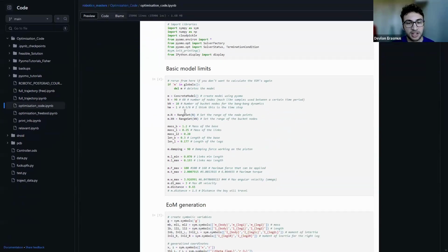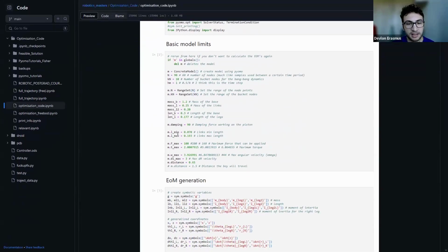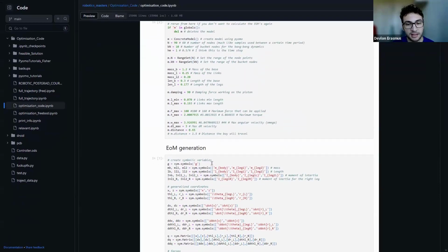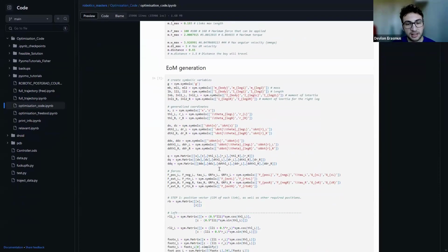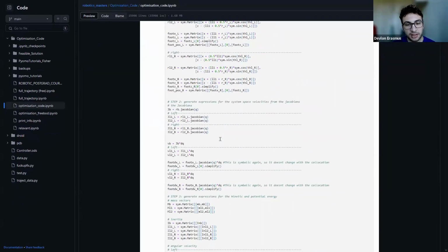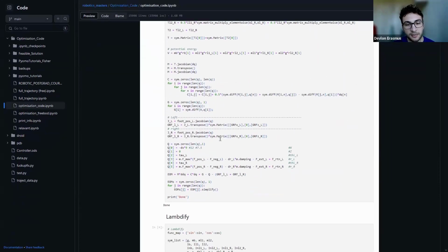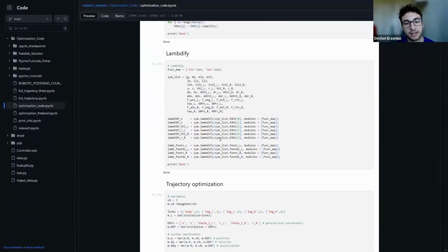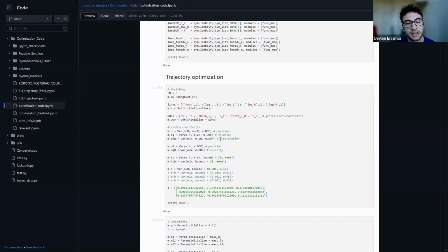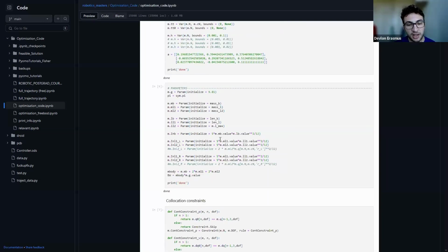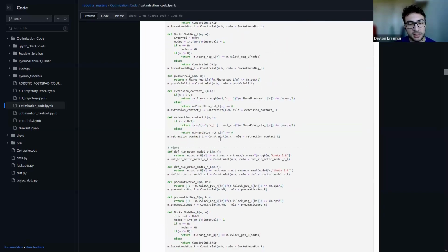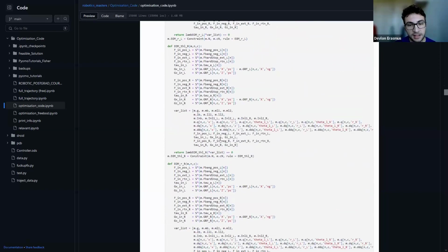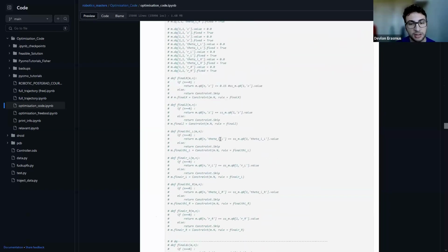So yeah, you set up the model, setting things like leg lengths and everything like that. Yes, all the constraints needed. And eventually, this is the equation of motions. Eventually, you go through the entire process of setting constraints, solving the manipulator equation, setting up gravity, setting up samples, the collocation I mentioned, everything like that. And eventually, when this thing solves like 8 times, you would reach a solution.